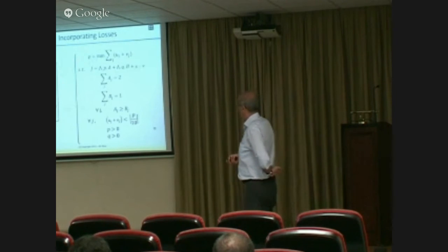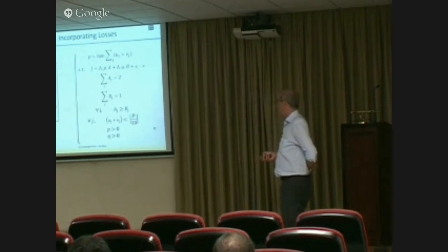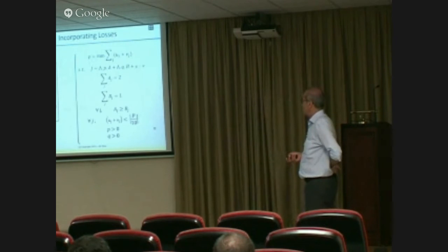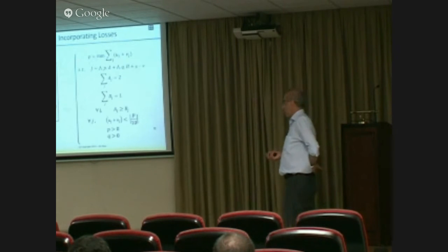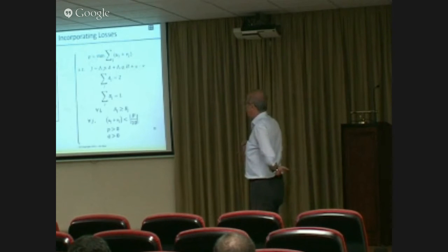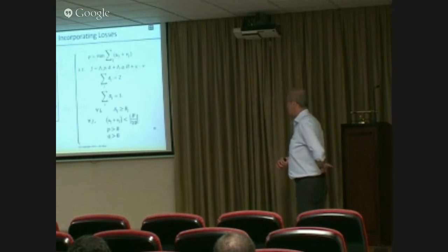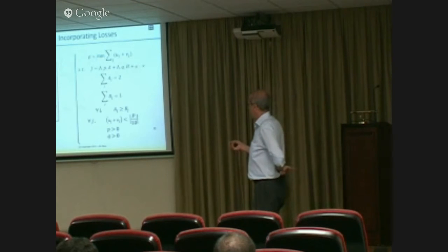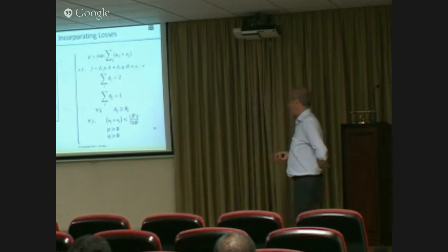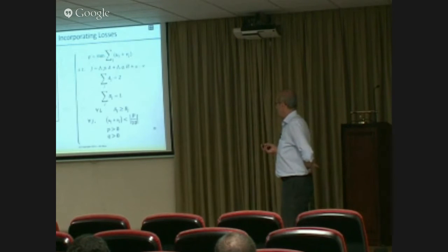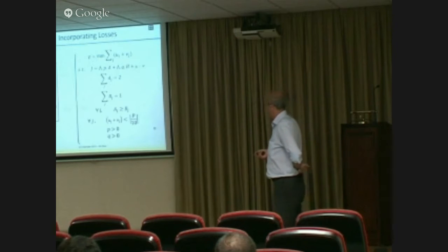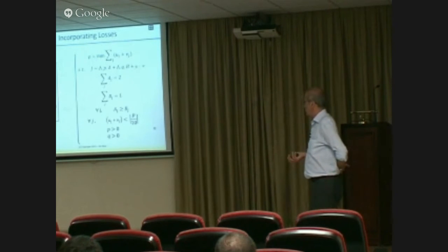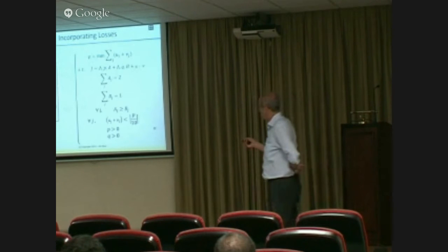And you get a solution. Now, obviously, the solution will not be entirely correct because we have been using the linearized model, which ignores the losses. If you introduce the AC model with losses, the 2 ends of these 2 pairs of injections will be different because of the loss along the line. So these 2 entries will not be P and minus P, but they will be different. And not only that, since it's an AC problem, we'll get additional errors.